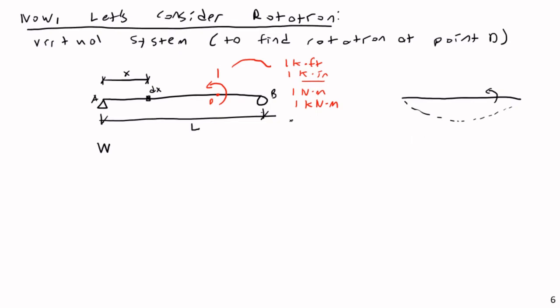So in the previous problem on lecture 17, where I worked through that long form example on trusses, I actually ended up getting a negative value for my final deflection. That didn't mean that the deflection was actually in the downward direction. It meant that the deflection was opposite the direction I originally assumed. Originally, I'd assumed a downward deflection in that joint. It turned out it was actually upward because of the way I had that truss supported and designed. Getting a negative didn't mean I got everything wrong. It just meant that it was going the opposite direction. So same thing here. You can assume positive, and if you get a negative value, that just means it's deflecting or curving in the opposite direction.